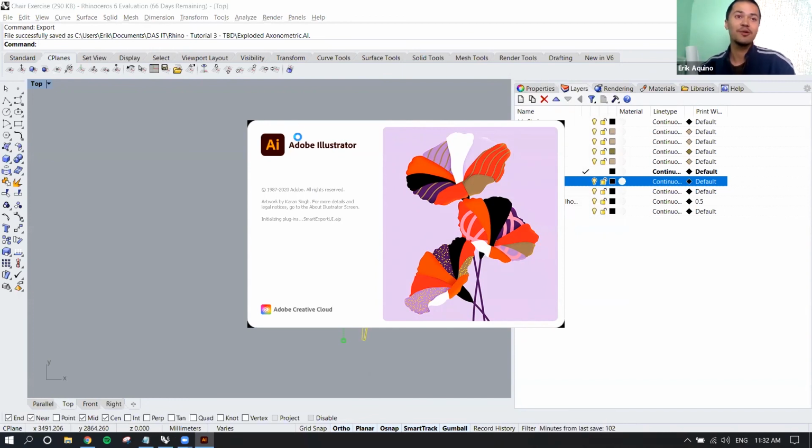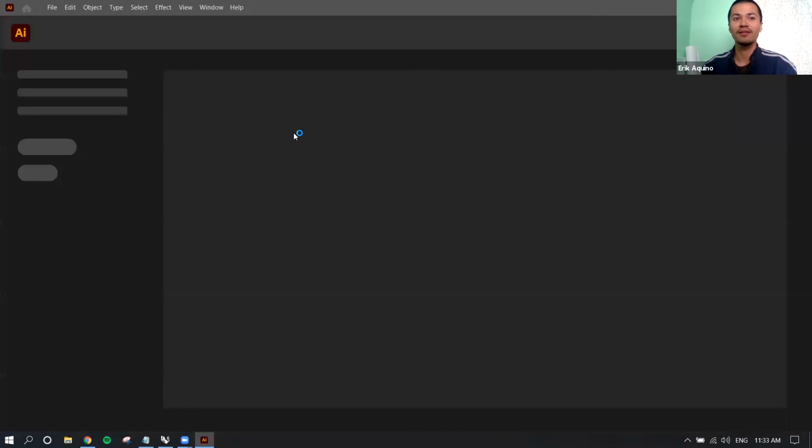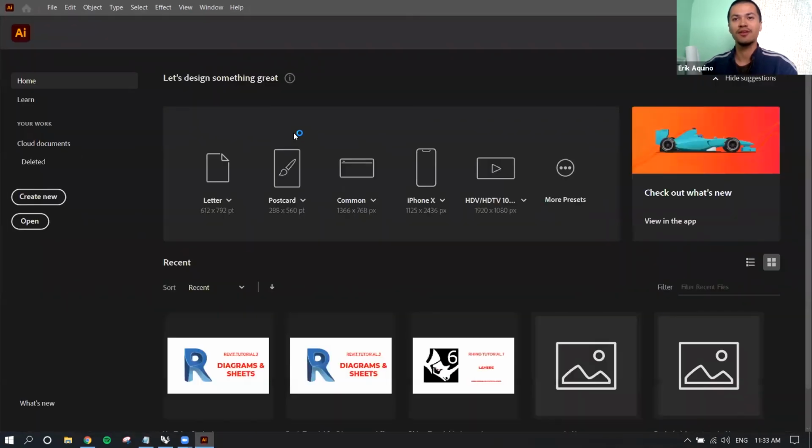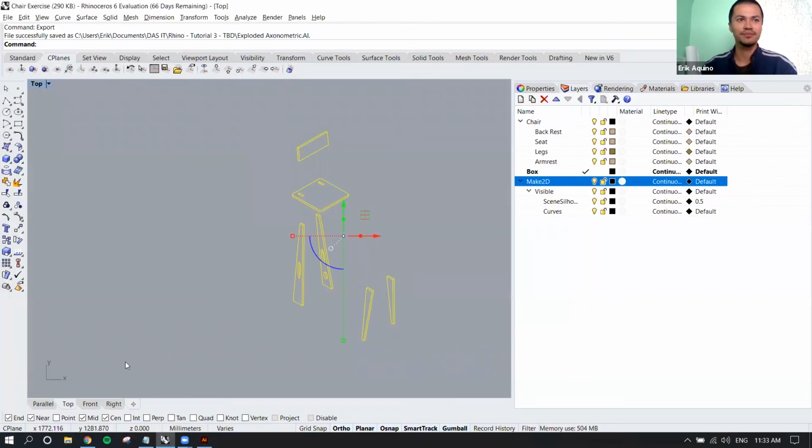Or I could do that now. So what we learned today was construction planes can help aid the process of modeling, especially when you have unique angles that aren't orthogonal to the default work plane in Rhino. And so you could set these work planes to your angles and even create a mobile construction plane that adheres to a surface or an object even when it's moved or modified.